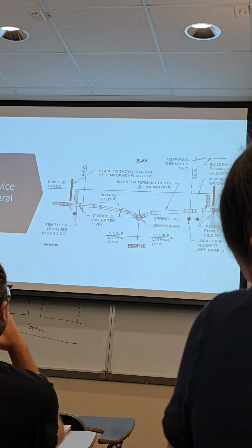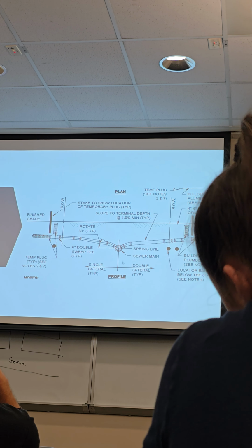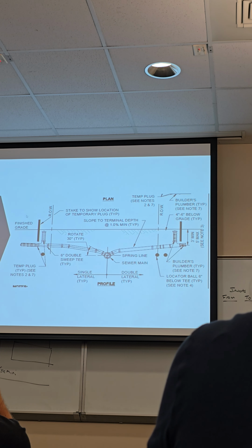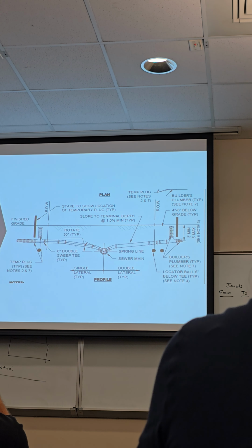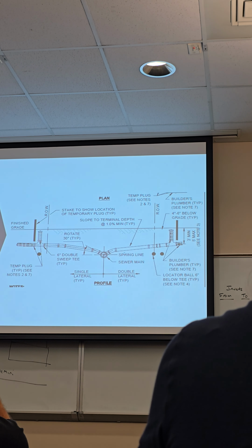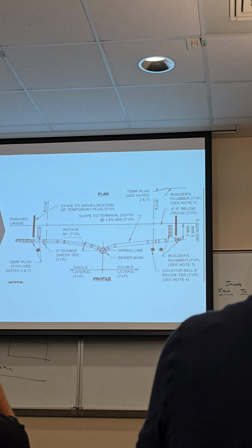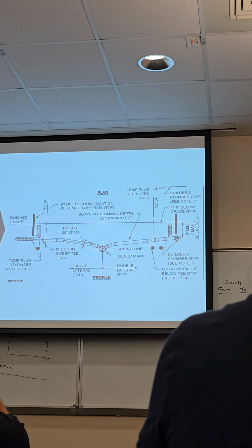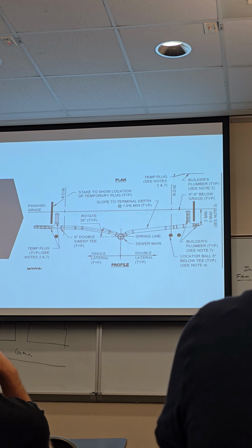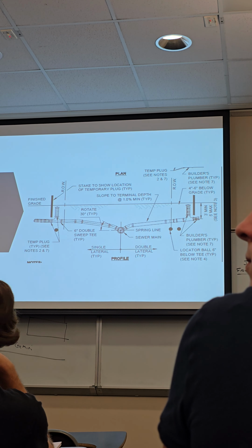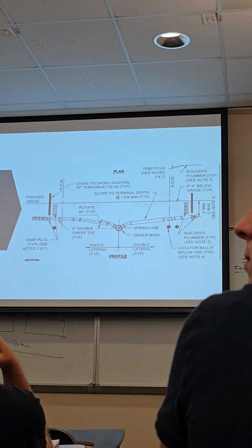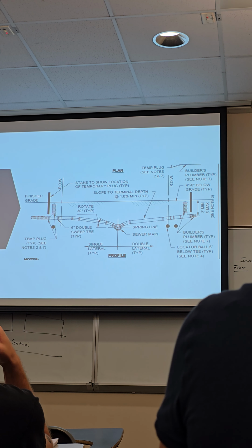So this is a sanitary pipe running down the center of a residential street. Again, here's where it gets in on either side. So every lot would have a lateral pipe that would connect into that main gravity line. That's how that's built. Yes? When we're doing our cost assessment, are we gonna need to add any laterals? We'll show that. We'll include it.